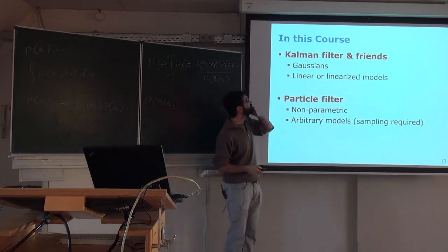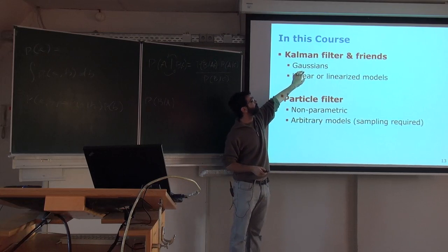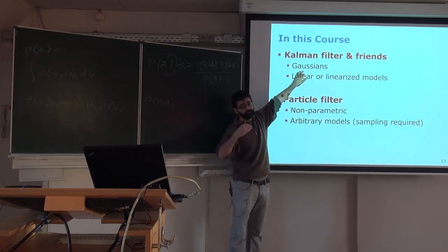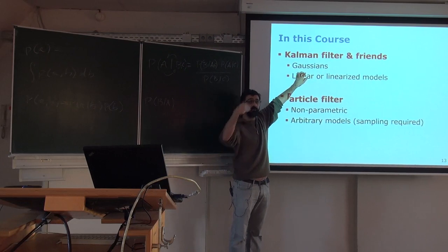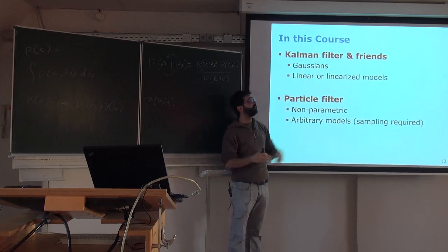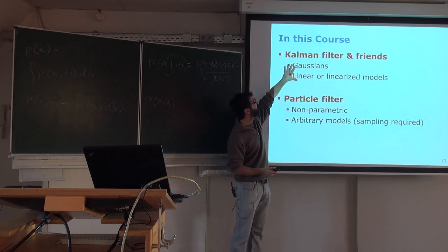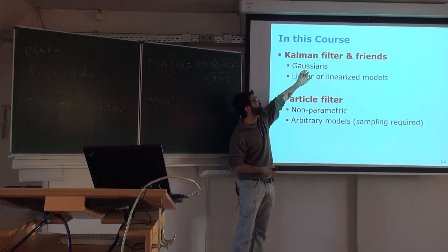The main assumption is that the noise is Gaussian, but you cannot propagate this Gaussian noise over the motion models and the observation models if they are nonlinear functions. When you propagate a Gaussian random variable through a nonlinear function, you end up with a random variable which is no longer Gaussian distributed. So they actually handle this kind of problem, but the main assumption is that all these models have